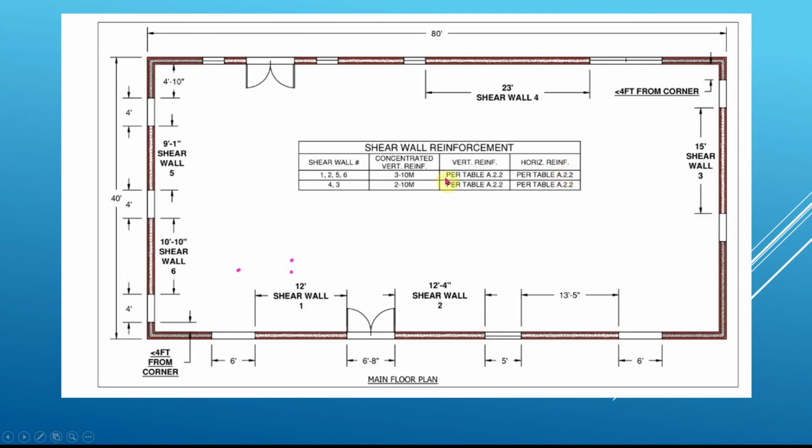And if we go back here, those shear walls, all four walls, need to be continuous down to the basement with dowels. So if you look at this one here, it's a 12-foot piece. I'm going to need those walls in the basement, right? That carry it right down to the foundation. So it'll pose some challenges for you folks.